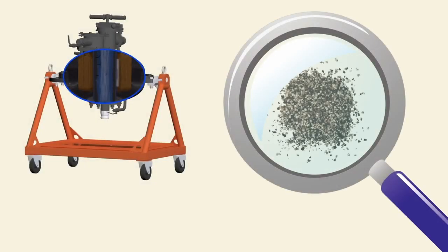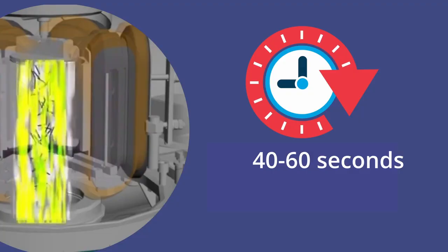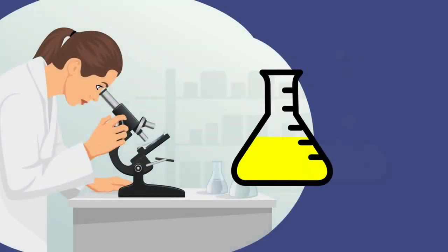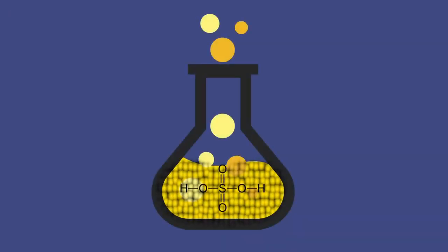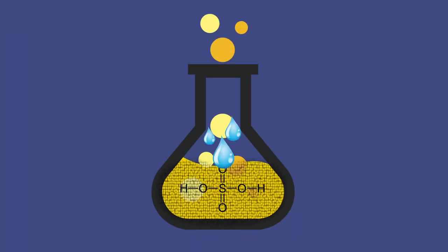Thus, experiments on grinding of ilmenite concentrate in the AVS-100 vortex layer device showed that processing for 40 to 60 seconds is the most efficient for further interaction of the ground material with sulfuric acid. After grinding, the samples were decomposed in sulfuric acid, which took just a few seconds, then they were diluted with water to the required concentration without being removed from the device's operating chamber.